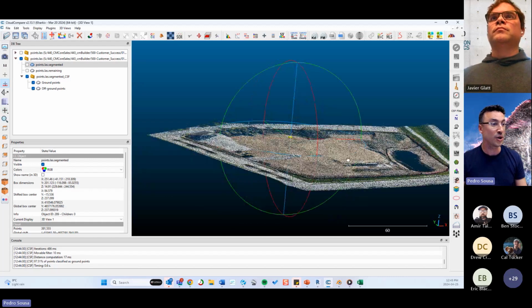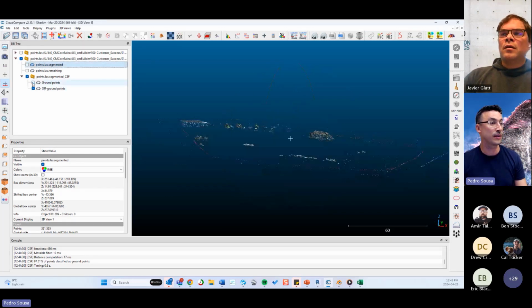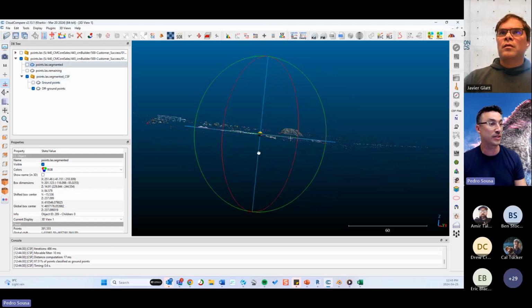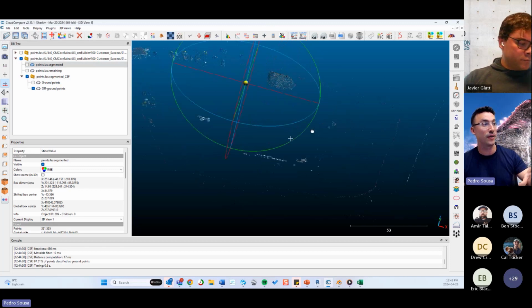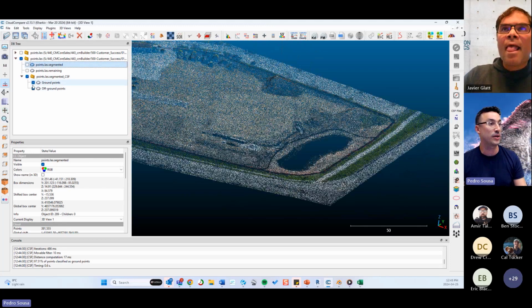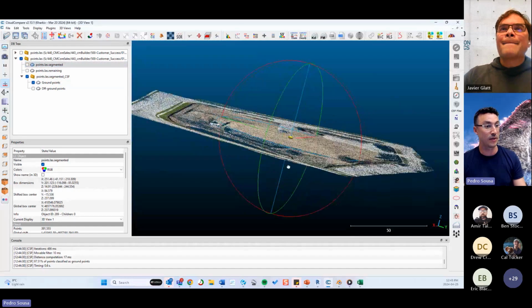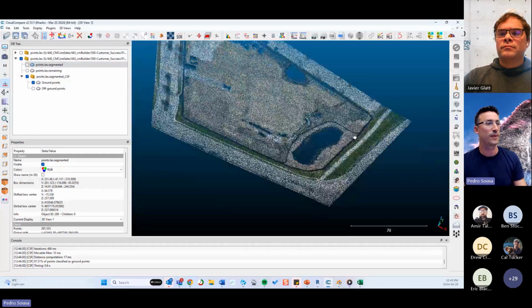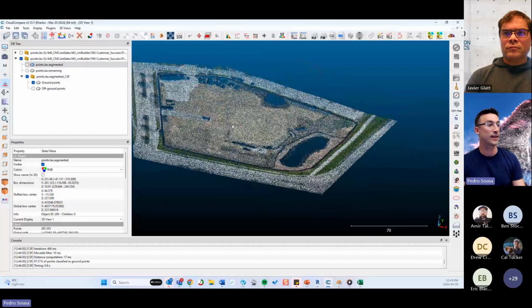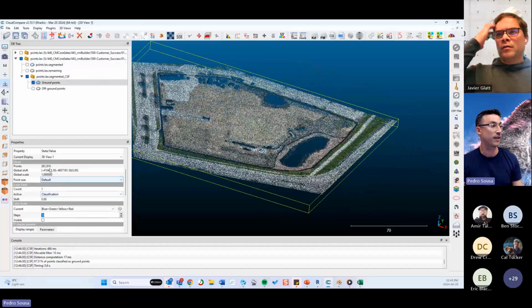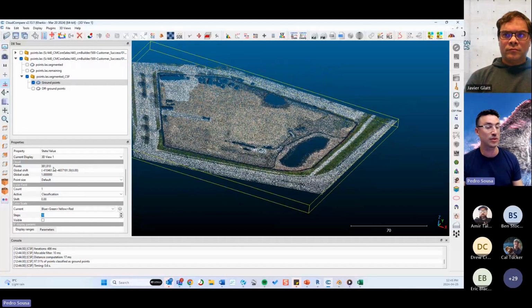Cool. So now I can choose over here, if I deactivate the ground points, you see, these are all the points that are represented over here that are not on the ground. And if I keep the ground points, these are the points that are on the ground. So it's quite smart. I really like this tool. Cool. And the next step now is for us to select this and see how many points we have left on this point cloud. So my point cloud was exported as 500,000 points, but after what I did, I'm left with 380,000 points. That's still too much.